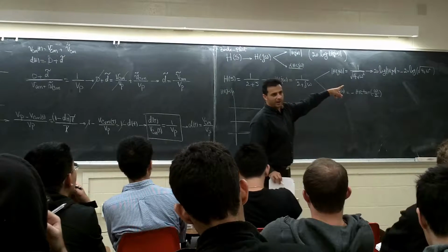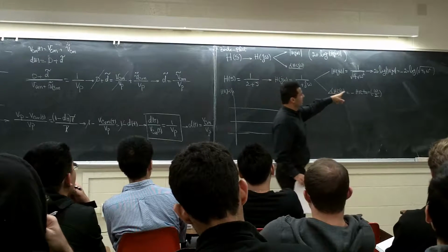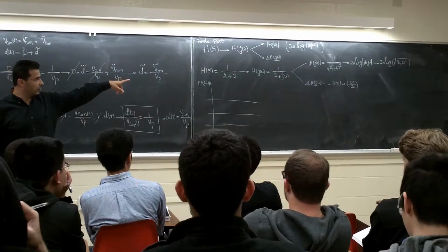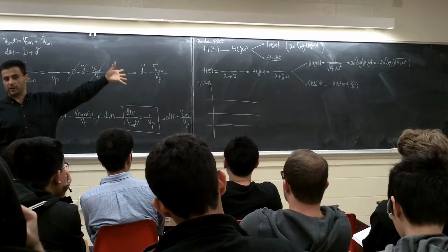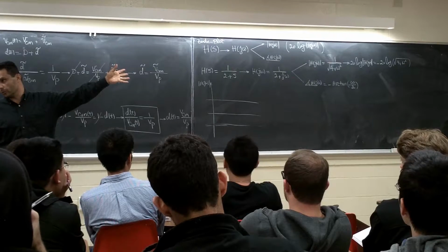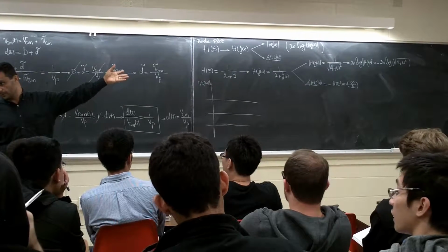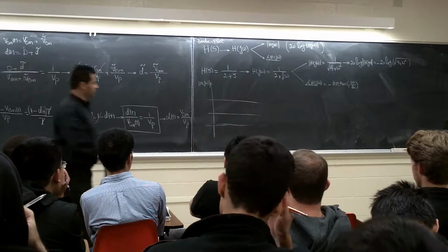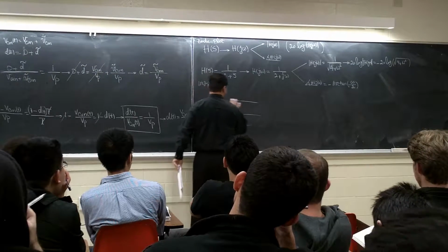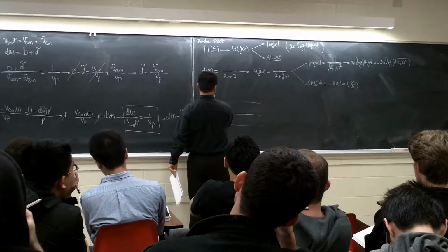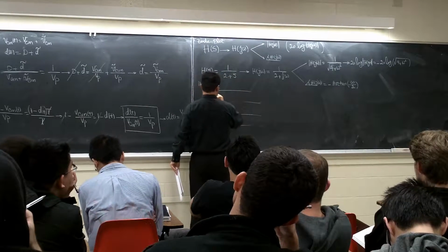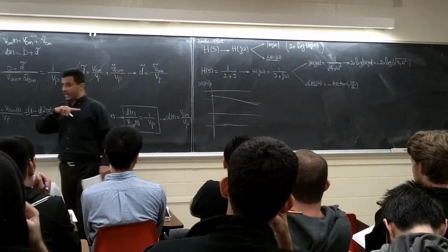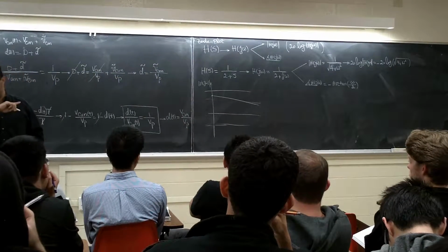But you say if omega is 0, how much is the gain? The square root of 4 plus omega squared. If omega is infinity, it's going to be infinity, right? Log of infinity is infinity, but it's going to be times minus 20, so it's going to be minus infinity, right? Basically, if you put it on the logarithmic axis, you're going to start from here and go like this, right? The omega axis is logarithmic, and the gain axis is linear.